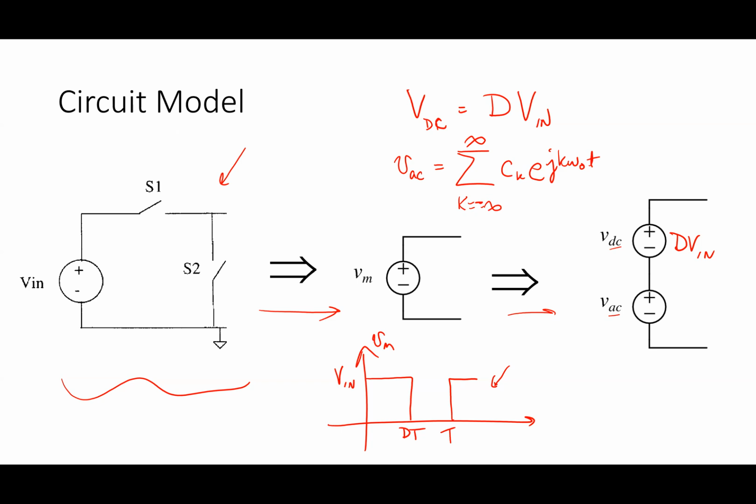Let's say, what do I want to do? I want to make a variable DC voltage source, right? And I can easily make that variable DC voltage source if I could do what in this last picture? We did that with the LED here, right? So remember, this guy's flashing, but you don't see the flashing. What is the flashing? The flashing is this part, right? And you're not seeing the flashing, right? So what do I want to do? I want to add a low pass filter that gets rid of that stuff and make sure that I don't see it.